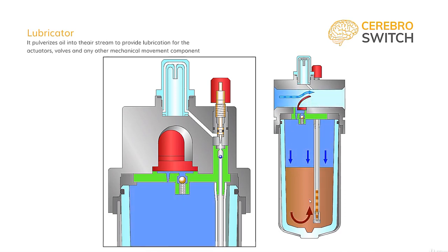There, like in a hairspray, pressure will push liquid up the straw through a screw adjustable cross-section. This is used to adjust the number of oil drops we want the air to take. On the top, there is a see-through drop channel to be able to supervise the operation. One caution this component has, and you really have to be careful about it, is the need of turning off the pressure when refilling.